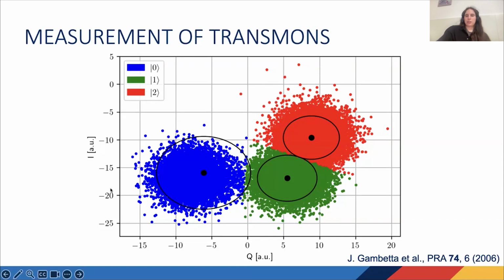And the way I actually quantify that state is by plotting the two components of the readout signal against each other and seeing where on the plot that data lands. And these plots can look different for every different qubit and processor that you're working with. So you do have to characterize them beforehand.